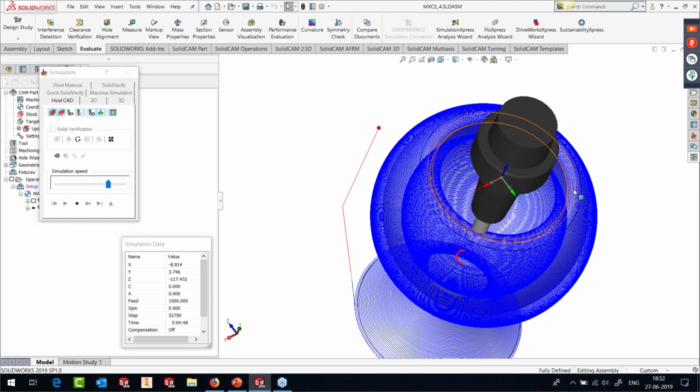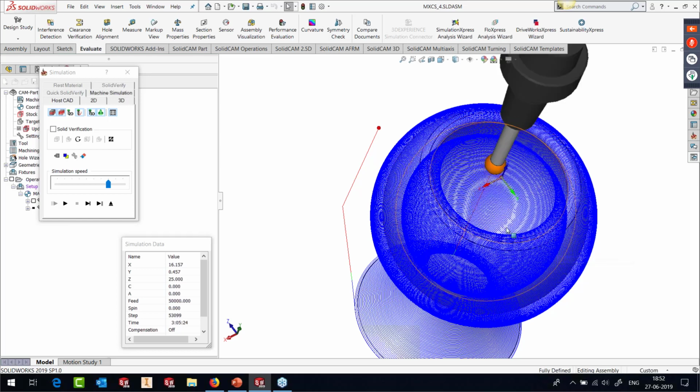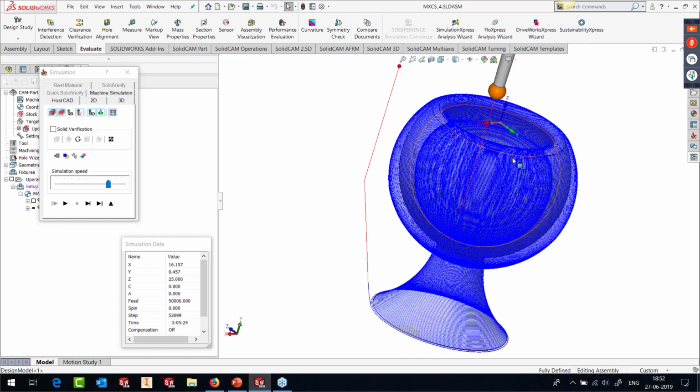For those customers who are using SolidCAM generic 5-axis morph between two curves and parallel to curves, the multi-axis constant step over can be a big quantum jump in terms of both the handling of difficult surfaces and also getting a very consistent tool path with exact spacing between the two strands of the tool path.